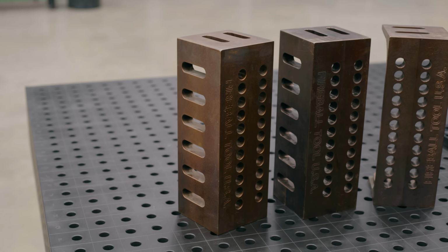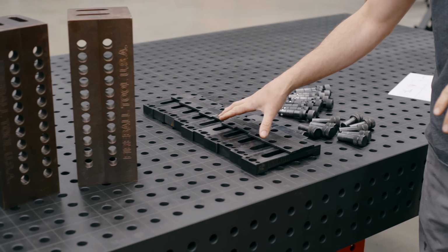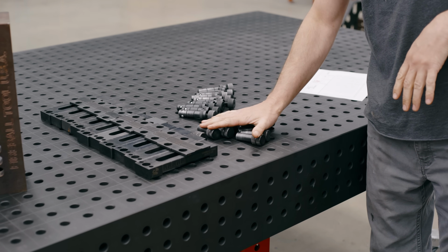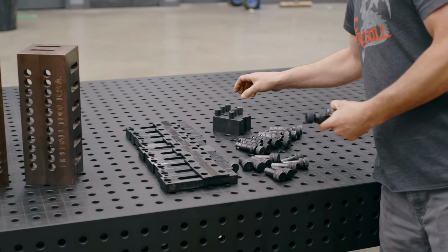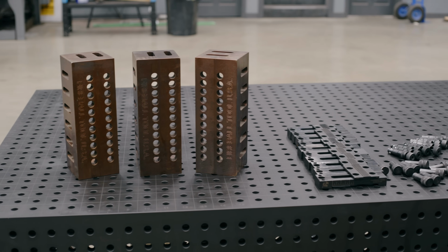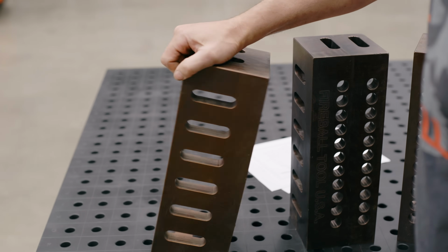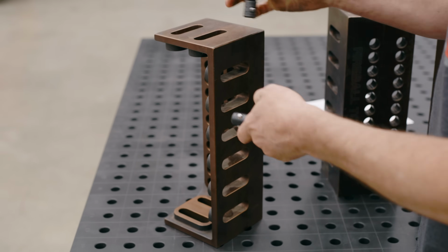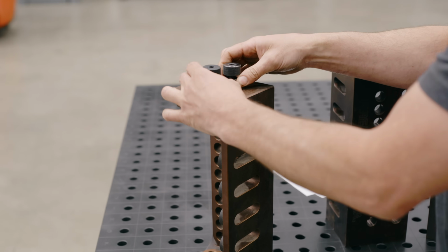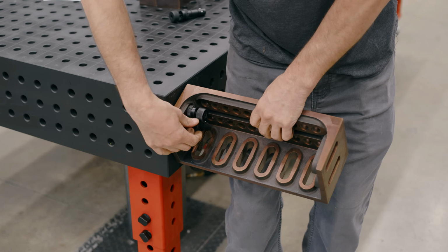All right, to get started, we're going to need 3 tower blocks, 10 tooth blocks and washers, 10 tacking bolts, 10 anti-rotation pins, and 4 fence blocks. All right, let's start with the tower blocks. We're just going to follow the map. These things are pretty cool. They have slotted holes going one direction and the other, but we're not going to be using the slots. We're going to be bottomed out into the ends of the slot so it doesn't move. It goes like this.